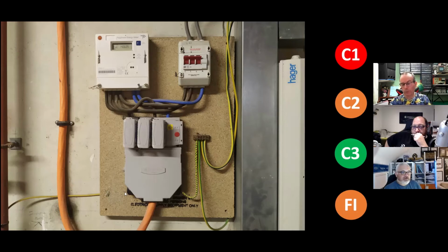Bit of a mess. And it's PME as well. Yeah, I was going to say, first question is what supply type is it? It's PME, and God forgive whoever used that insulating tape around that cable. It just sickens me to my stomach, that. Earth bar looks like it's seen better days as well. It looks a bit rusty and corroded.